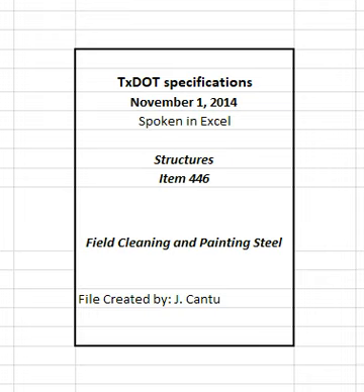4.8 Paint improperly applied. To uncover evidence of improperly applied paint, the engineer may at any time during construction explore underneath the surface of any paint coats already applied. Repair these areas of investigation at no additional expense to the department. Whenever unsatisfactory conditions are found, the engineer may require remedial measures.